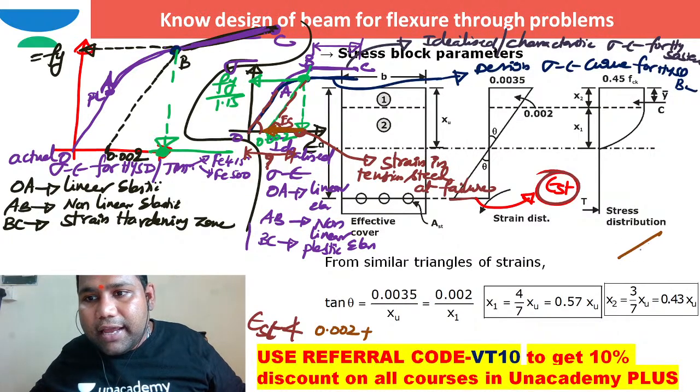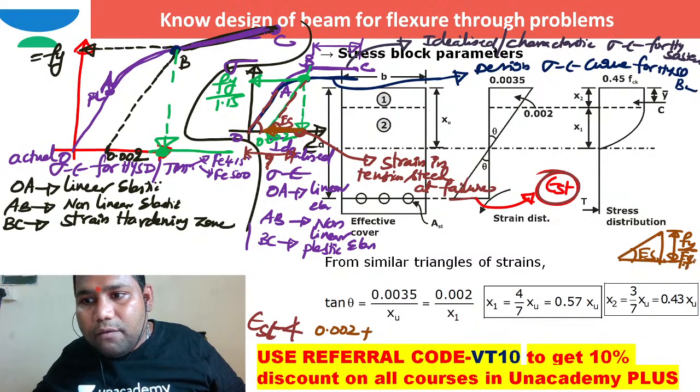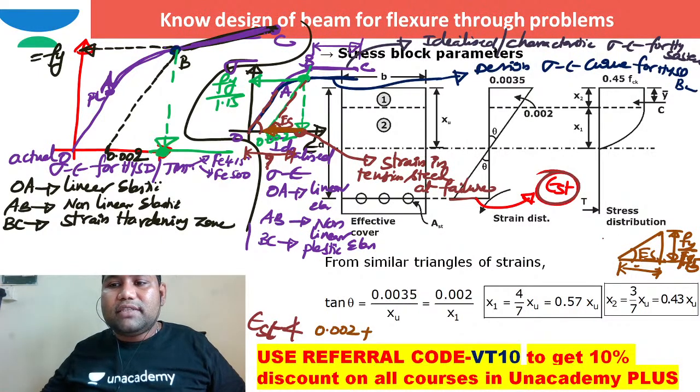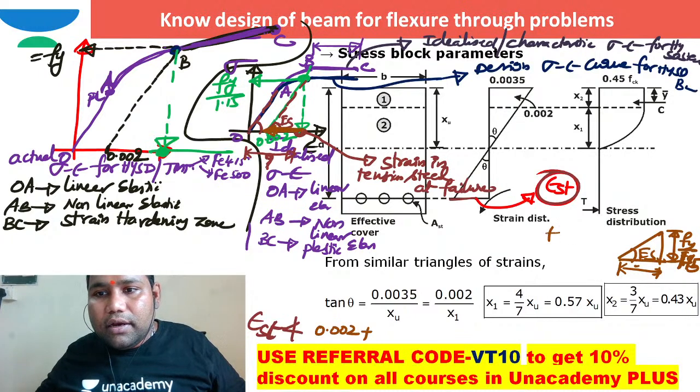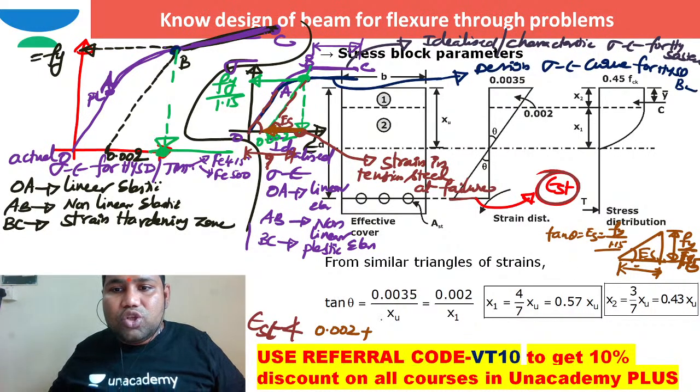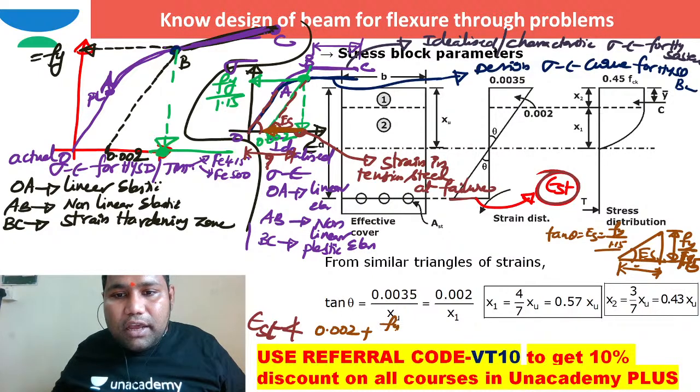If you take it this way, this is Young's modulus of steel. This opposite side is how much? Fy by 1.15. And what is this question mark, this horizontal distance? Young's modulus Es is equal to tan theta, which is nothing but Fy by 1.15 divided by this horizontal distance. So how can I write that horizontal distance? Fy by 1.15 into Es.